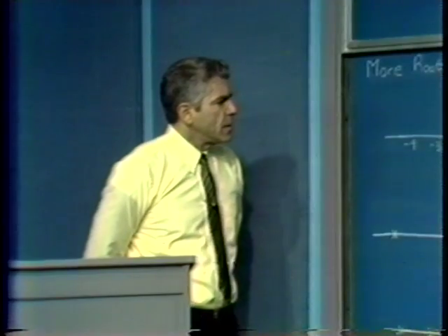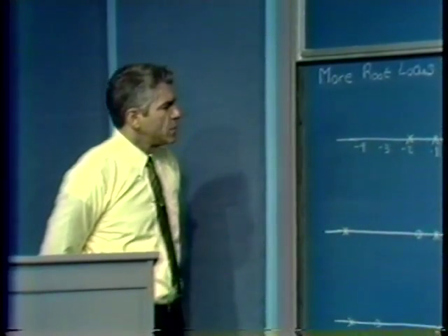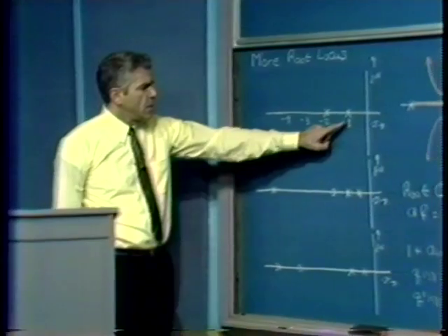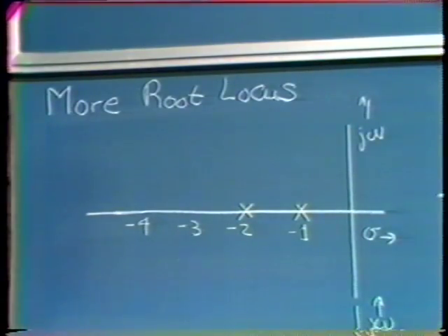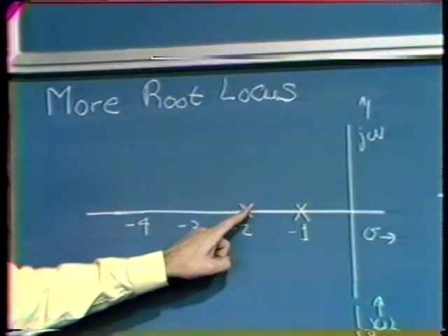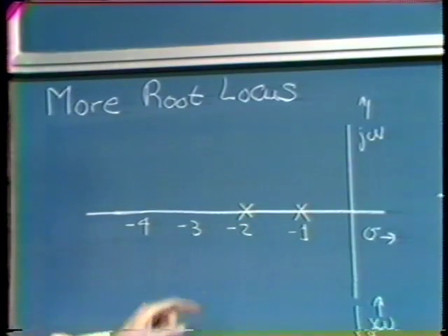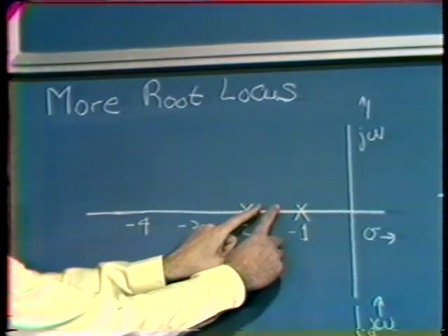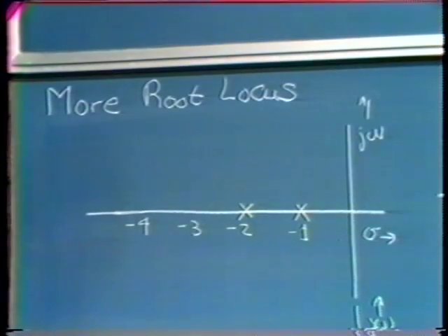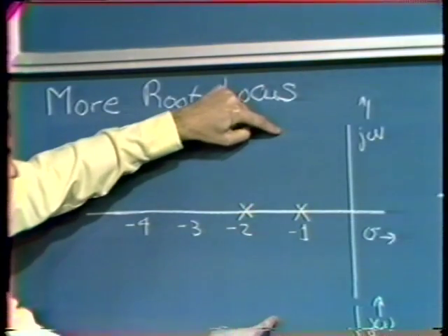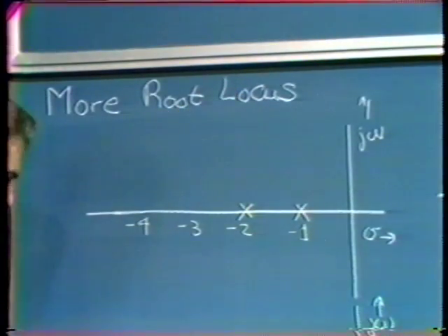Let's start by looking at a second-order system. In other words, assume that we have a loop transmission that has two poles associated with it. We've looked at that configuration before, and recall that we found out that if we do a root locus diagram for that system, the two branches come together on the real axis, split off, and then further increases in A0, F0 result in a progressively smaller value for the damping ratio associated with the resultant closed-loop complex conjugate pole pair.